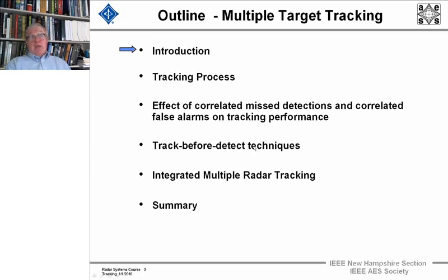And then I'm going to talk about another detection tracking technique, which is called track before detect, which really means assemble an awful lot of data, of detections at low threshold where we have a lot of noise, and use hypothesis testing to see if there are sets, with a very heavy computer burden, of detections that will follow a track nicely at the expected velocity and state vector that you expect the target to be.